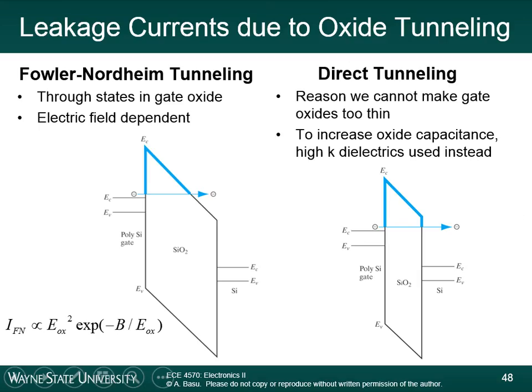All right, a high K dielectric is a dielectric with a high relative permittivity. This increases the electric field in the material, so it increases the interaction between the plus and minus charge. It makes it easier to invert the channel. So the other mechanism is Fowler-Nordheim tunneling.